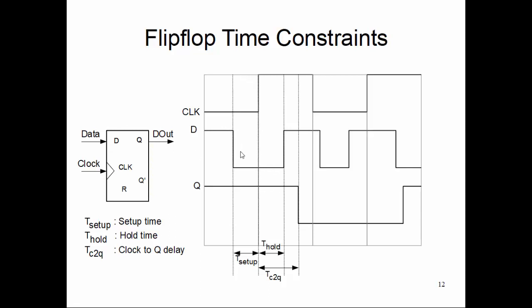The Q side, let's see, it was 1, I want to make it 0, and so on and so forth. So D I must set to 0 so that next clock cycle your Q output of the flop becomes 0 from 1. So I cannot do it arbitrarily